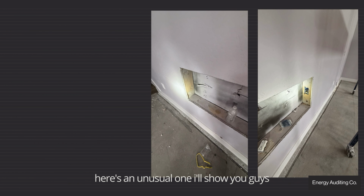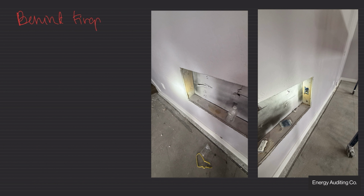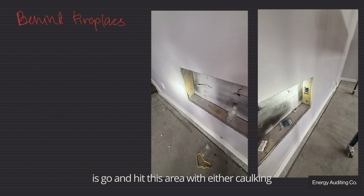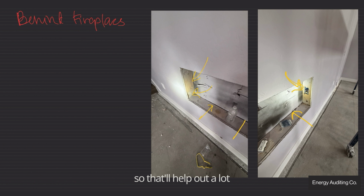Here's an unusual one I'll show you guys, and it's behind fireplaces. What I would recommend this contractor does is go and hit this area with either caulking or expansive foam all along in there. You want to get the stuff that's fire rated if possible, something that can resist all that high heat. So that'll help out a lot.